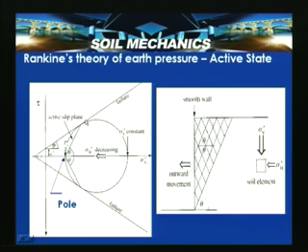So, this failure plane, when you draw a line from this point to the point where it cuts the failure envelope, the inclination is nothing but theta, which is 45 plus phi by 2, where phi dash is the friction angle. As the soil is homogeneous, it can have a failure plane like this, and it can have a failure plane like this. So, this failure plane actually represents the failure plane which is here.